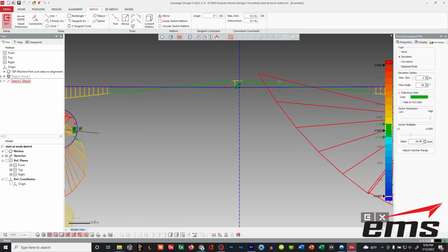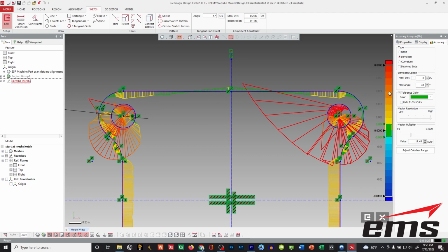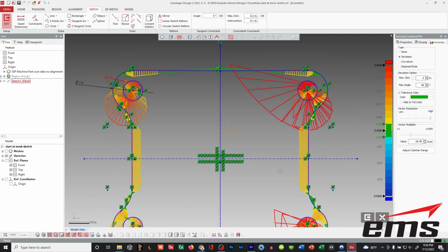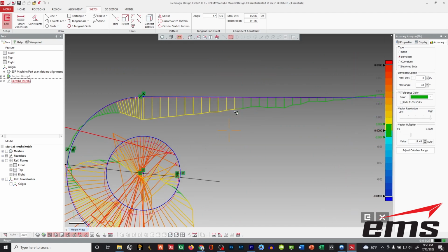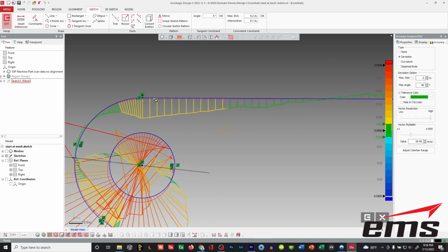Okay. So you can see these little whiskers are color coded. So green is good, but then approaching red is out in the positive direction. And then approaching blue is in the negative direction. And anywhere I can highlight along here and see what that deviation amount is. And if you zoom in on the line, you can see that pink line and these little whiskers definitely correlate with each other, right? Because it's undersized here, and you can see by how much.